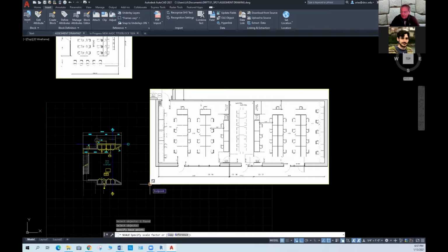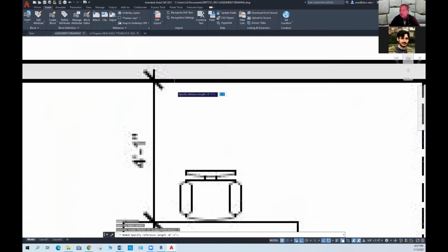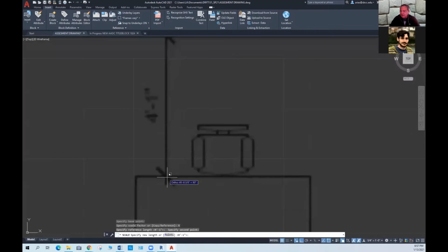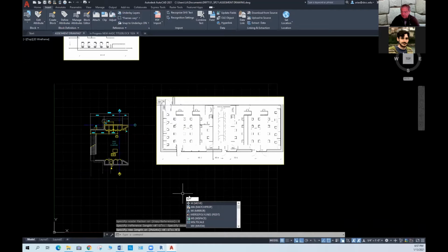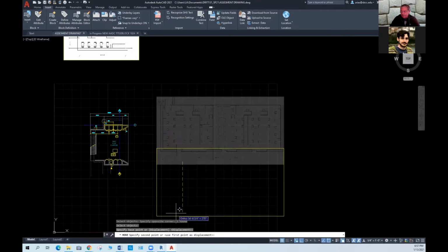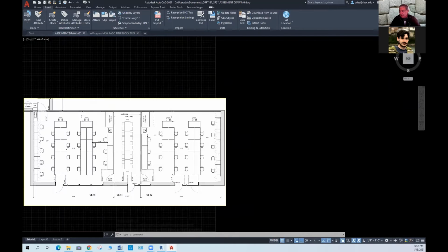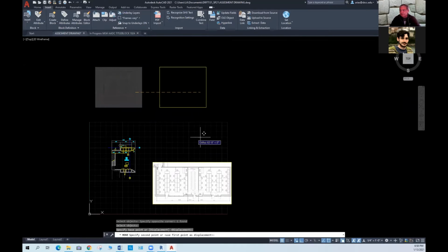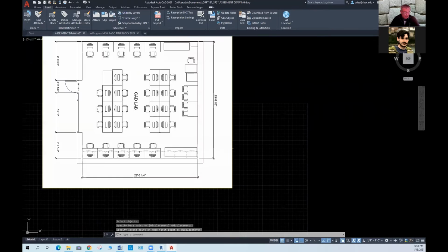Now I'm going to do R for reference, see? And now the reference I want is that I want the distance from here to there to be 4 feet 1 inch. And now this image is to scale. Let's do the same with this one, although remember that this info here is the same as this area here. So I'm going to move it and rotate it.